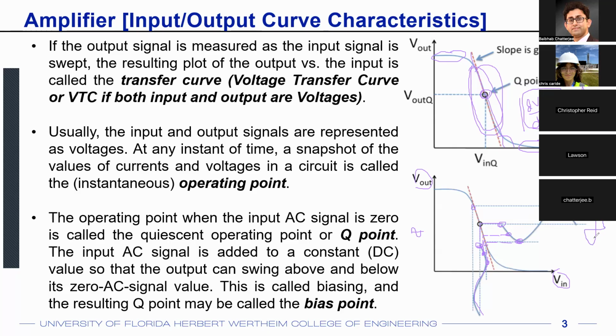And that is what is meant by having a negative gain. The negative gain does not mean that the value of the signal becomes negative. Right? If you apply, let's say, a 10 millivolt AC, at the output, it does not become minus 10 millivolt. And there's no meaning of a minus 10 millivolt there. But what minus 10 millivolt means is that it's the same 10 millivolt, but with a 180-degree phase shift. So if your sine wave of the 10 millivolt had a positive cycle first and a negative cycle after that, at the output, you'll first have the negative half cycle and then the positive half cycle. That is what is meant when you say my gain is negative.